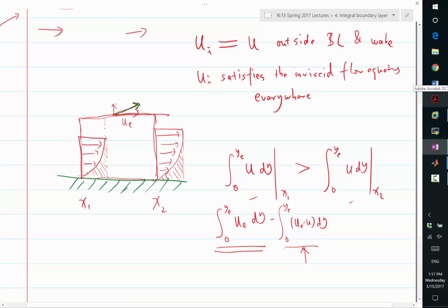Any non-constant in the X directional velocity has to be somehow balanced, right, by the variation in the Y velocity when you travel along the X direction in order for me to have zero vorticity. And because I know that the X directional velocity dominates, my Y velocity in the boundary layer is much smaller than the X velocity. So the X velocity should be almost constant. Therefore, the X velocity of the inviscid flow should have a basically constant velocity profile, right?